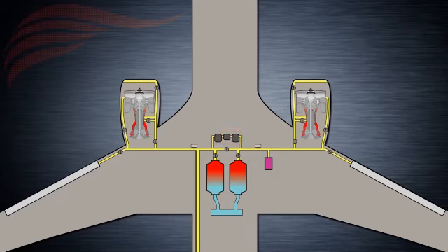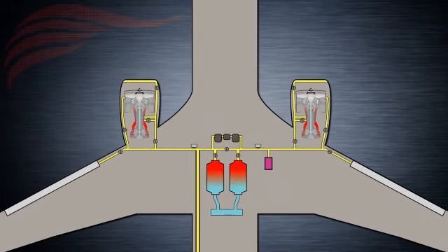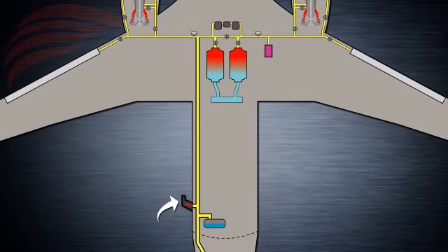Similarly, the left side of the manifold relates to the following systems with bleed air: Engine 1 bleed air system, Engine 1 start system, APU bleed air system, left air conditioning system, left wing anti-ice system, hydraulic system A reservoir pressurization, total air temperature TAT probe, water pressurization, and isolation valve. It's not necessary to memorize what system is associated to what side of the pneumatic manifold.